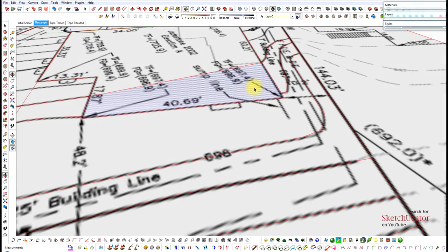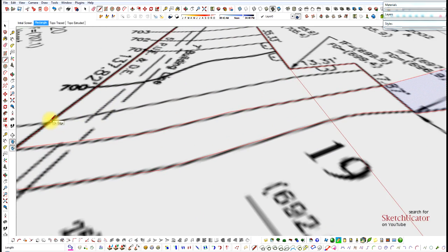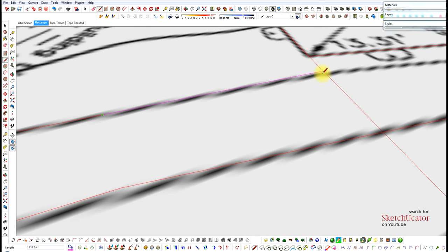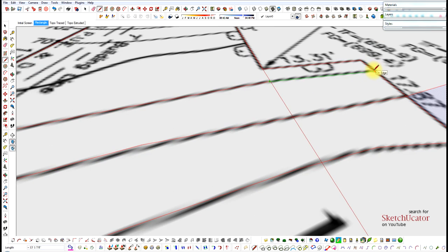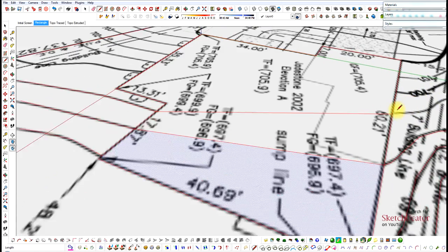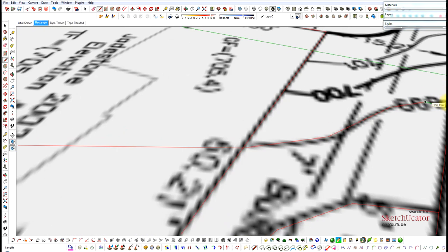I do want to cut right through the house because I want that topography not to get messed up by the house. You'll see later that the tool we're going to use in SketchUp would actually treat that rather badly if I essentially leave a hole in the middle of this site plan. So again, go right through the house. Making sure you do hit the edges of the house and hit the edges of the site. You want all these to intersect properly so you have the right faces happening.